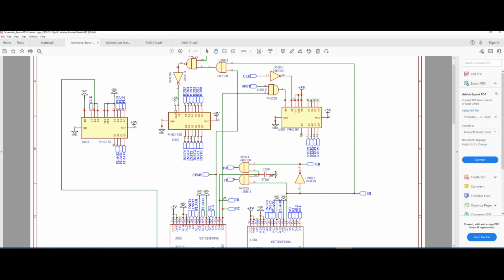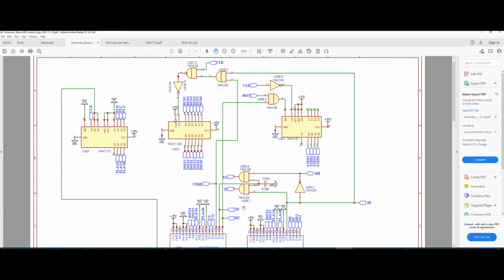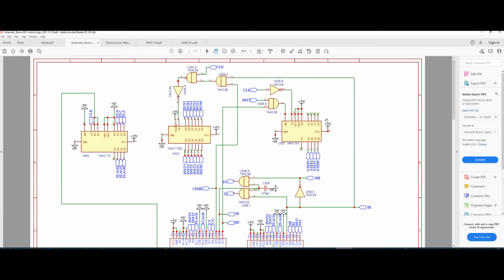All right. So I think I have mentioned that signal in the slides, but let's have a look and see what it does. Basically, when we are counting here and going through all those micro steps from 0 to 16, or excuse me, from 0 to 15, what will happen is that if we don't have control logic here, the counter will continue to the next step until it reaches 15, and then it's going to reset to 0. However, if you think about a lot of instructions and the micro instructions inside an instruction, you see that we don't necessarily have 16 steps.